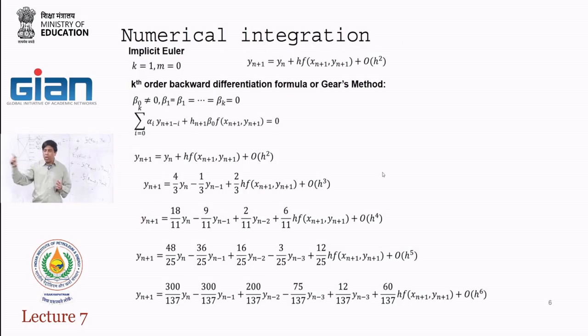When you click those options, and I will show you today where it is, this is actually what is happening. Higher order means lesser error, but it can be computationally more difficult, because of the terms it is keeping, and it becomes more difficult for it to converge.